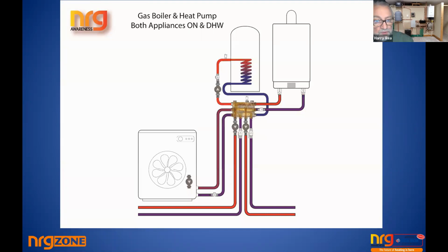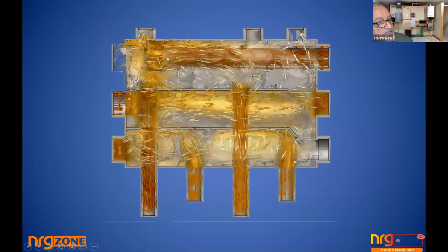So now, we thought we saw everything, and now we have the strangest thing of all. Just suppose we've got a system working at a low temperature and high temperature, but we want a high temperature cylinder, but we have low temperature here. So what if we took the cylinder from this corner? Now when the heat pump delivers across with its say 40-degree water, the gas boiler takes say 25 litres a minute, just suppose, or 20 litres a minute up here.